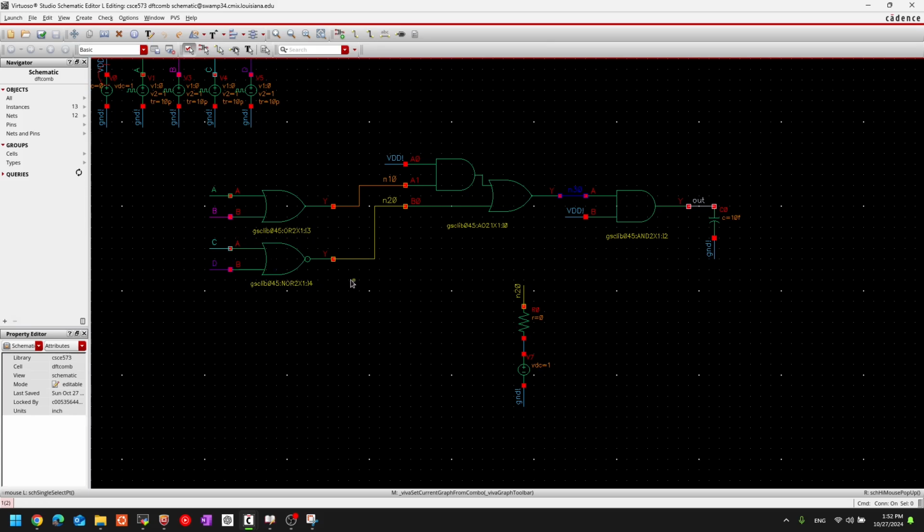All right. So that's the reason why you have a high steady state current. Otherwise, when the circuit is functionally correct and behaves normally, there wouldn't be a steady state current. So there wouldn't be a potential difference between N20 and the output of this NOR gate.